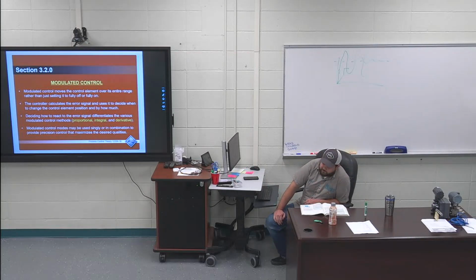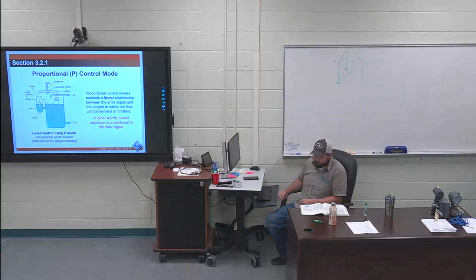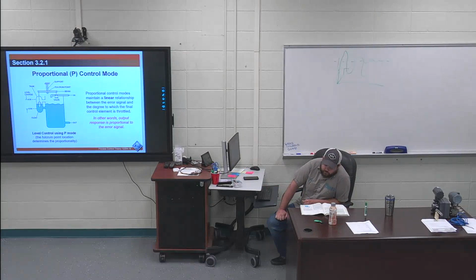The whole second paragraph is highlighted in 321. Another type of control is available in which the final control element is throttled to various positions that are dependent on the process system conditions. A proportional controller, also known as a gain controller, provides a stepless output that can position a control valve at intermediate positions as well as full open and full shut. This is accomplished by a lower gain with the controller.